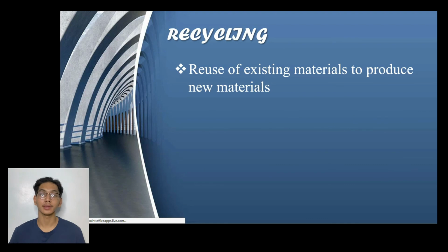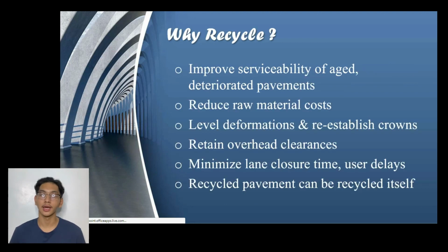Another technique in pavement rehabilitation is called recycling. It is simply defined as the reusing of the existing materials to produce new materials. A lot of us may ask, why use existing materials instead of buying and utilizing new ones? Here are some facts that may answer our questions. Recycling improves serviceability of age-deteriorated pavements, reduces raw material costs, levels deformations, and reestablishes grades. It also retains overhead clearances, minimizes lane closure time or user delays. Also, recycled pavements can be recycled itself.